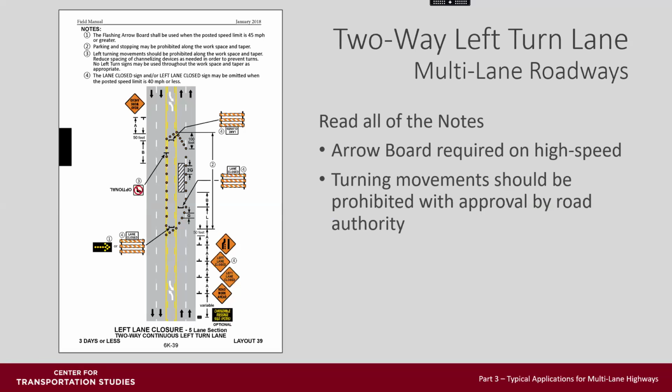For this operation, it's important to note that the left turn lane tapers are only 50 feet long, since this is not open to through traffic, only to vehicles making a left turn. Also, place no left turn signs as required by the governing road authority. Please note that arrow boards are required for this operation on high-speed roadways.